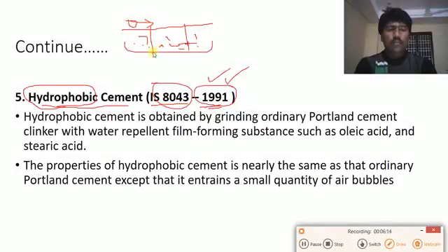In order to make these piles or towers here, you need to place the concrete inside the water. So whatever concrete we are placing here should be made with hydrophobic cement. Then only can it be resistant against the water.